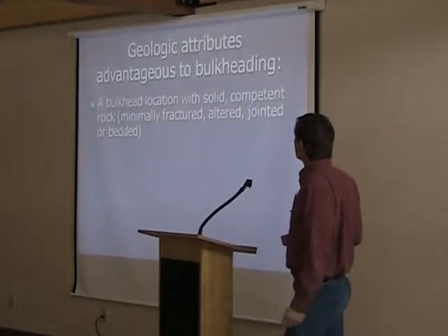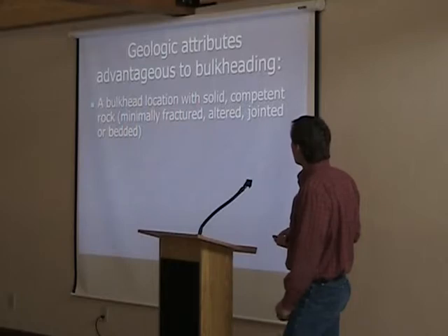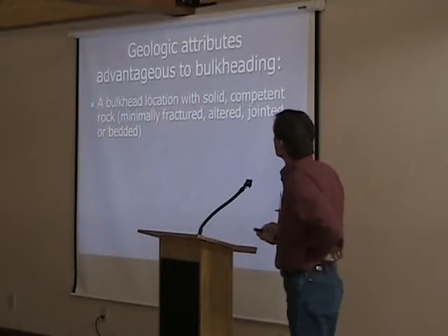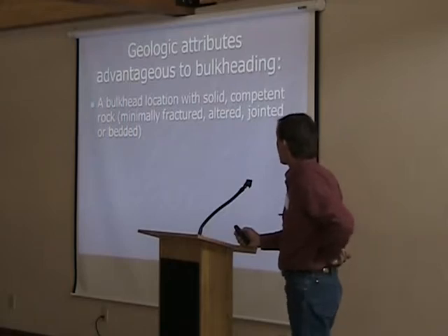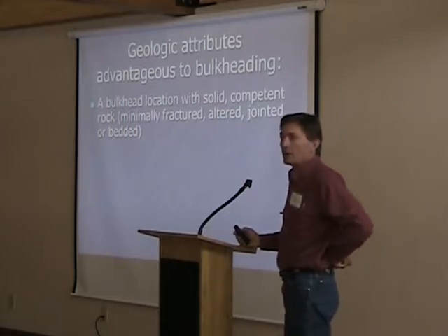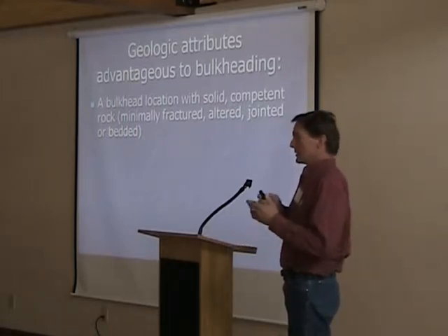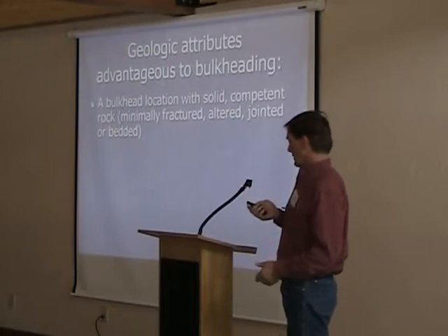So I'm just going to run through some geologic attributes. As we talked about, we want solid, competent rock. We're trying to find an area in the workings that are minimally fractured. We don't have alteration or joints or large discontinuities where the water is going to leak into.